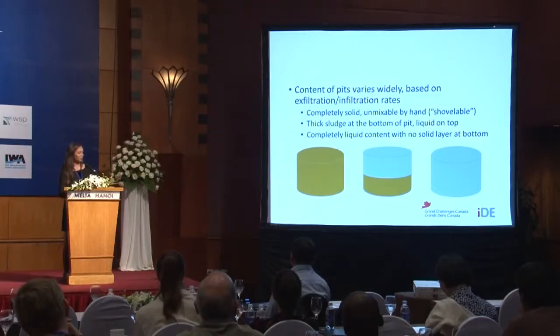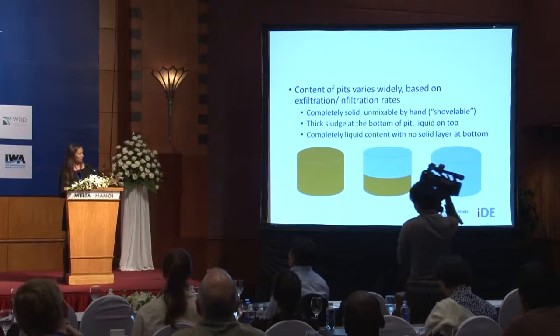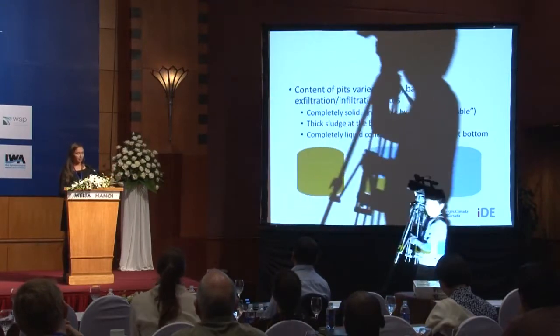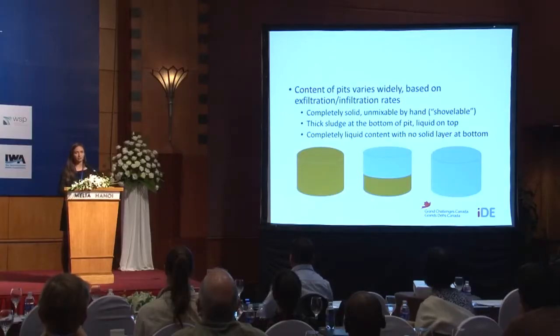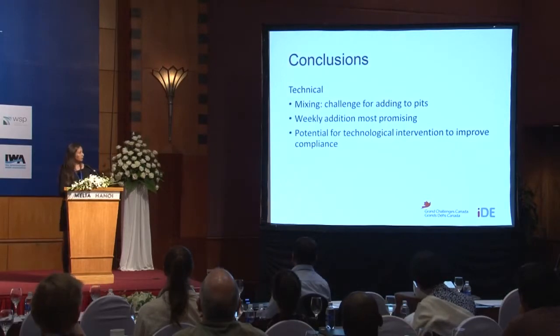as we heard earlier, there's a very high diversity in the kinds of sludges that are present in a lot of these pits. It varied greatly between completely solid, something that you could only shovel, something that couldn't be mixed, to a very liquid layer and a solid bottom, to completely liquid all the way down, even though, like I said, these toilets have been used for at least 2 years or longer. So some conclusions on the technical scale: mixing is a big challenge for adding lime directly to the